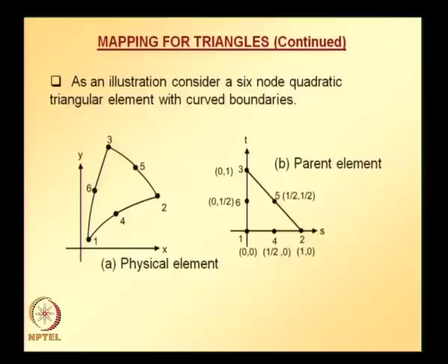So, with the information that is given for the parent element coordinates, we can easily derive the shape functions by calculating L1, L2, L3 for each of the nodes.